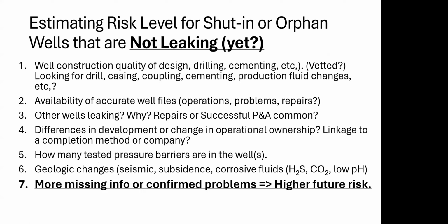All right, now let's estimate a risk level here for a shut-in or an orphan well which isn't leaking yet. And over time, I'm not saying that all wells won't leak over time, but most of them will go for a long, long time if they're done correctly. So look for well construction quality, the design, the drilling, the cementing. Is it vetted? Is it tested? Is it really designed well? Accuracy of the well files.